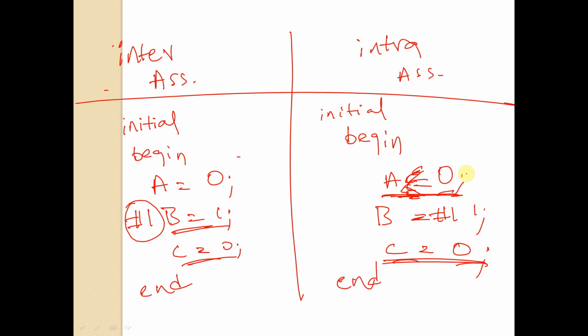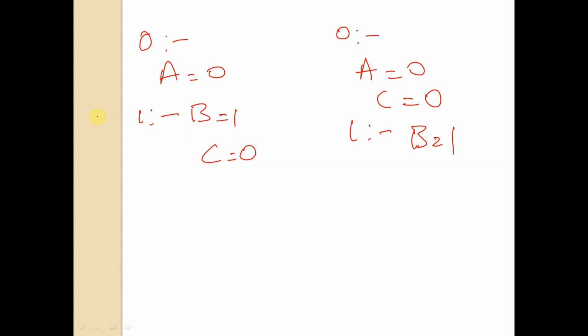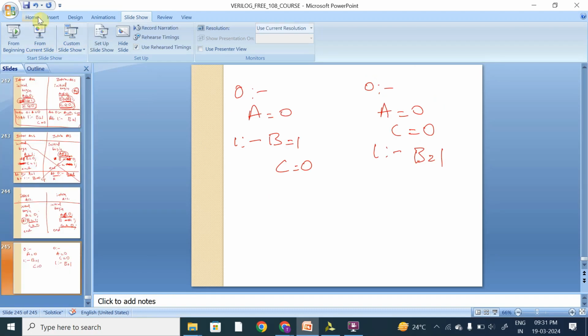So is it clear? Is it clear, right? Yes. So this is how inter and intra assignment delays work with blocking assignments and non-blocking assignments. So we can consider one more scenario here. Wait a minute. Or else I will directly show it with the help of the simulator.